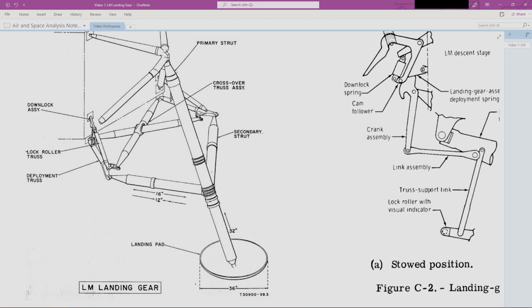Now, let's imagine you put just one secondary strut on. You've constrained one of the swinging directions, but these are both pin-type rod end joints or ball joints. So if we draw a line between those two joints, this whole thing, as a triangle, can still swing around that axis.